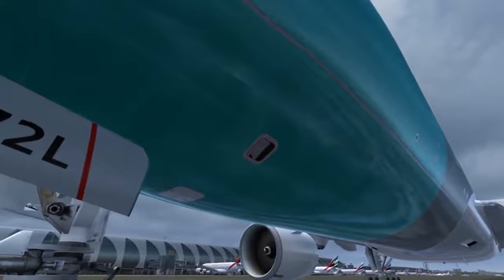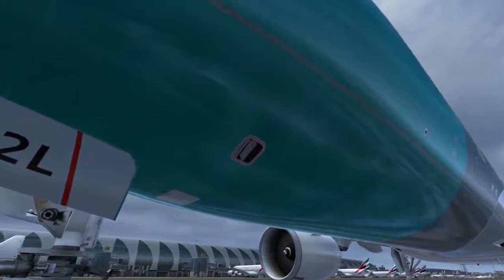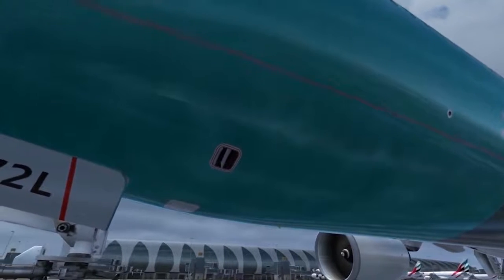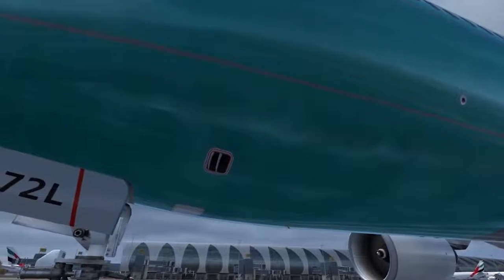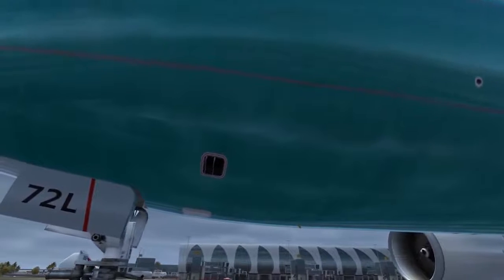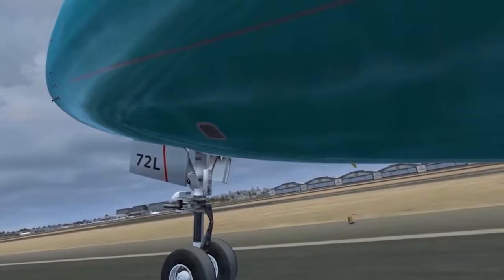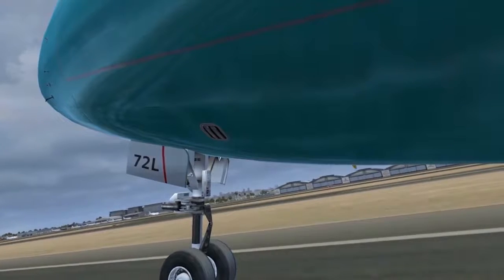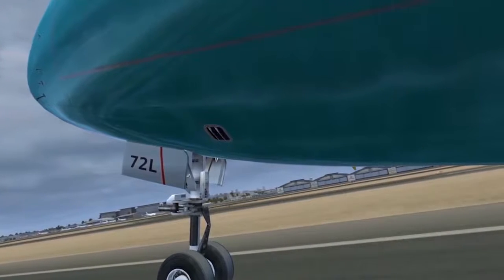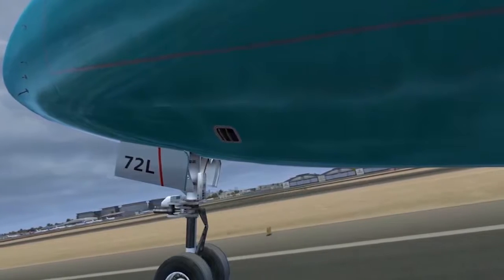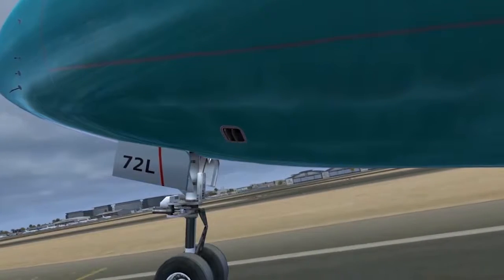On the ground, the ASCPCs command the outflow valves to a full open position to ensure that the cabin does not pressurize whenever the aircraft is stationary or during taxi to the runway. At speeds above 25 knots, and once the pilots have commanded the engines to higher than 60% N1 for a few seconds, the ASCPCs understand a takeoff condition and do the following.